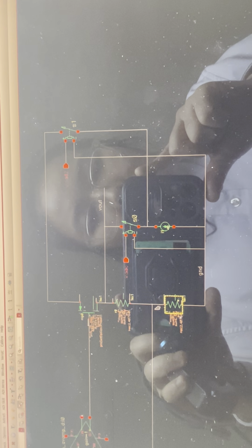If you wanted to simulate the worst condition, just to save you having to sim over all the corners, in your use file you could try picking the slow models, the SS models, with low voltage. That would be 2.25, I think we said, and a high temperature.